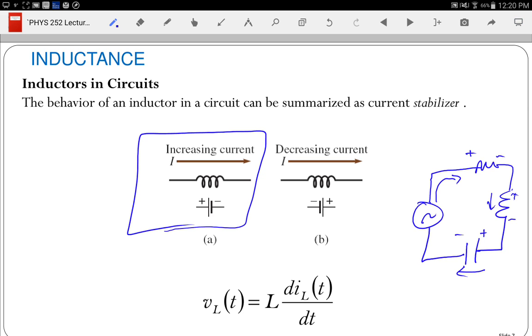If we had left it in there, we would have had the opposite sign convention, and then I would have had to use a different rule for how I define the positive and negative side for an inductor than I use for a resistor. Right, but I'm saying, if you worked out your equation and it came out positive, not negative, then you'd have to switch that. Well, it couldn't, but... Oh, I see. Okay, so this is the equation that relates voltage and current for an inductor.